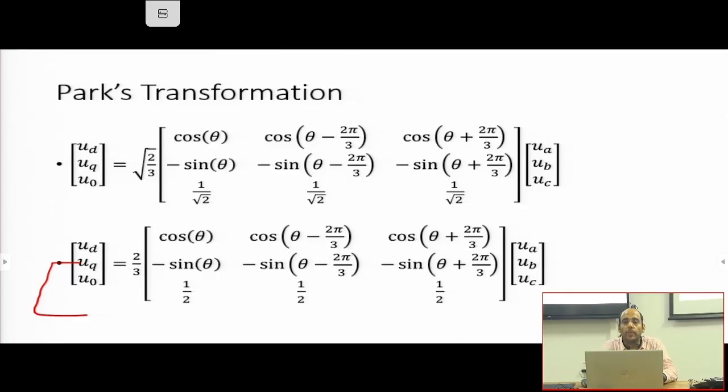Why do we do so? Because the control that we all know is the best for controlling real systems is basically a PI controller. And you know the transfer function of a PI controller is Kp plus Ki by S. Now for a DC system, S equals j omega, and omega is 0. So if you put 0, you get a very high gain. So basically it's a high gain controller, and when there is a high gain controller, your steady state error becomes 0.